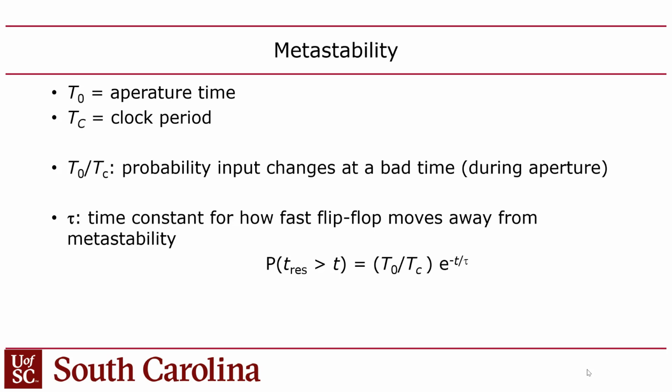Because the mobility, meaning the charge carriers in the P-type silicon, which are holes, are physically about half the speed of the electrons. You can't overcome that, and so you have to balance that by making the PMOS bigger. But in doing that, you increase the surface area of the gate, which increases the capacitance. It takes more time to charge up the gate of the PMOS, and as a result, the rise time is going to be slower. It's going to take longer to drag the output of a gate up to 1, whereas if you want to make it 0, you turn on the NMOS transistors, and because electrons are so fast, they pull down fast. So that's why the rise time is different.